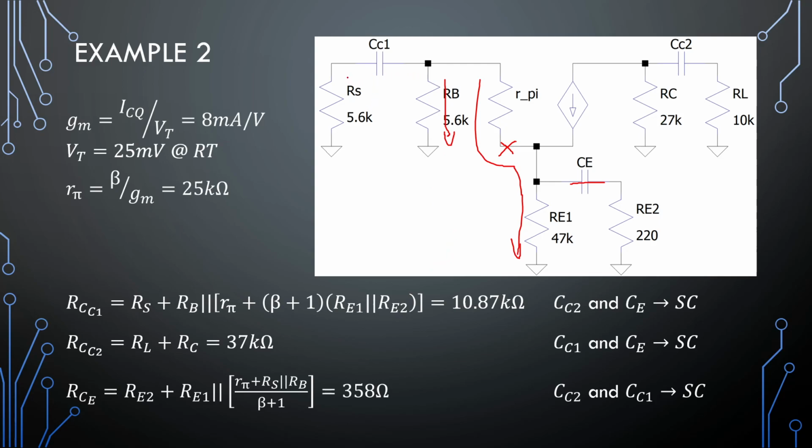Now, another way to look at this, when we were just working with a plain amplifier, looking past this capacitor, this was Z in. This whole thing right here is Z in. So if you did calculate Z in at some point, you can just add it to the source resistor. Right, RCE. Now that is when this capacitor is a short.